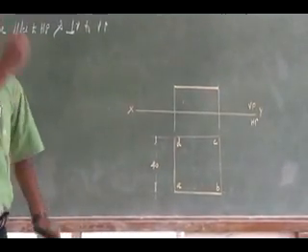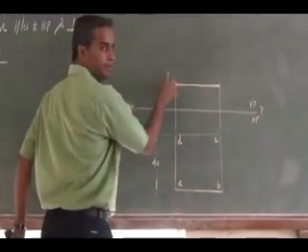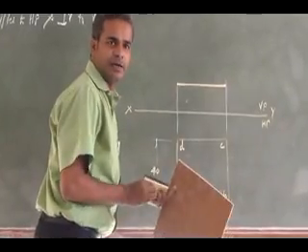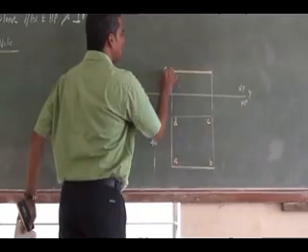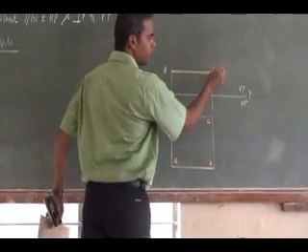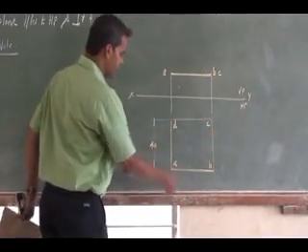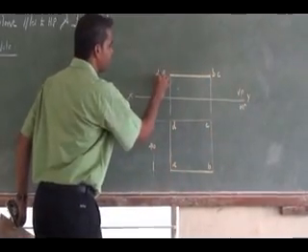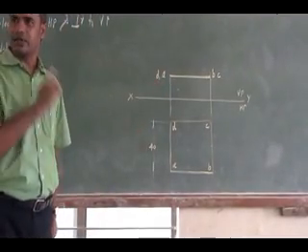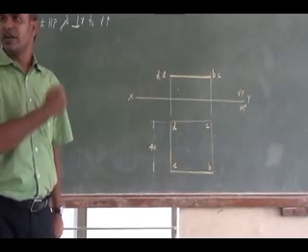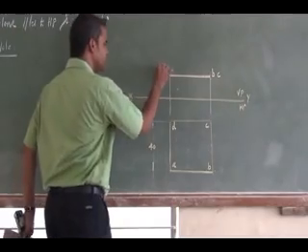Now you have to give the notations for the front view. I have my A here. In the same order, A is here, B is here, then there itself I have C, and there itself I have D. These are the front view notations, and we have to note them with a dash. See here, this is with a dash.